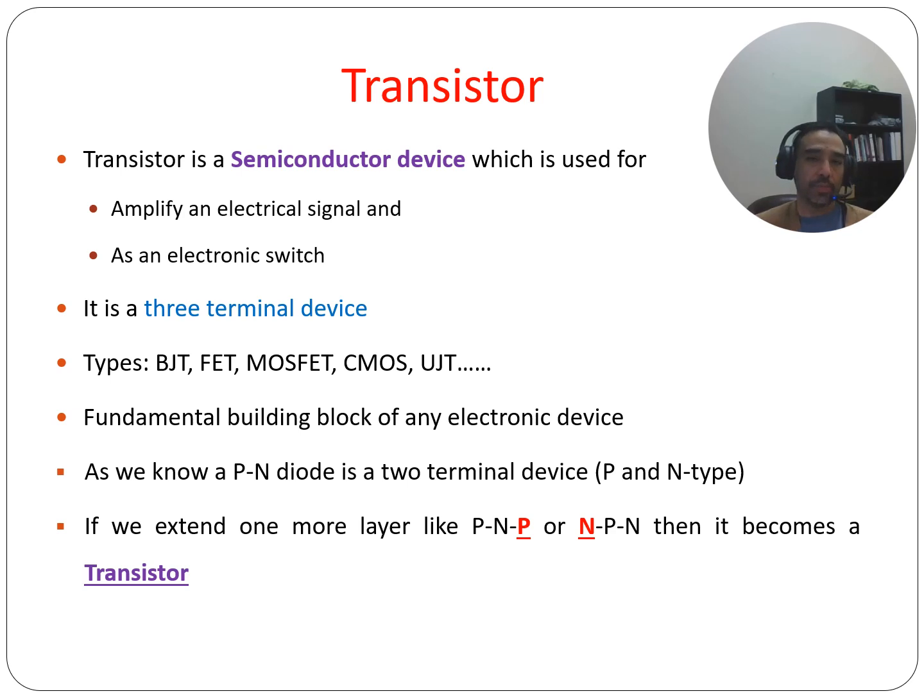And so what is this? It's a type of transistor that uses both electron and hole charge carriers to operate, just like our diodes. It works by having three layers: an emitter, something called a base, and something called a collector. So emitter, base, collector. Each lead is actually pertaining to one of those parts. And that's used for switching and amplifying signals. Again, these are just the highlights. We haven't seen them in circuits yet. And one key feature for BJT is that it relies both on electrons and holes as charge carriers for it to function. So it relies on both of those.